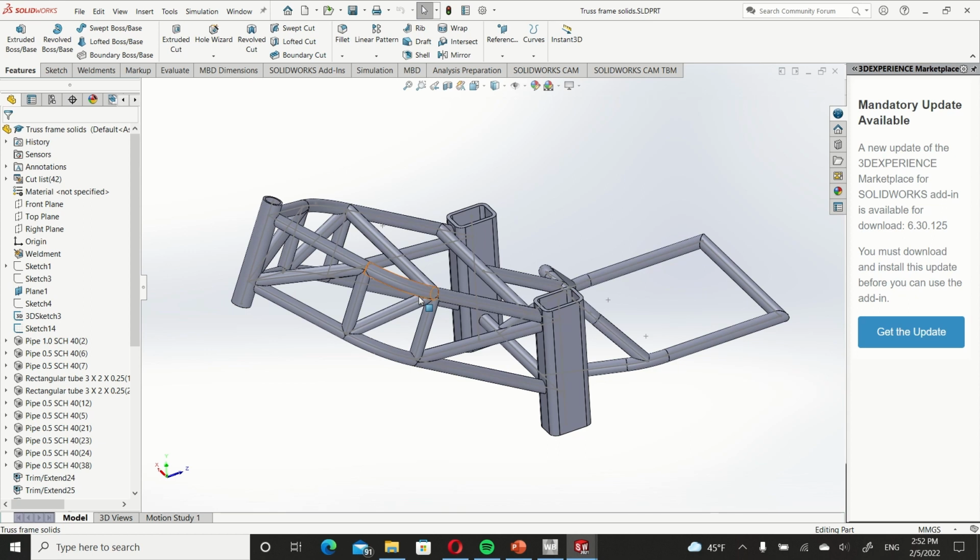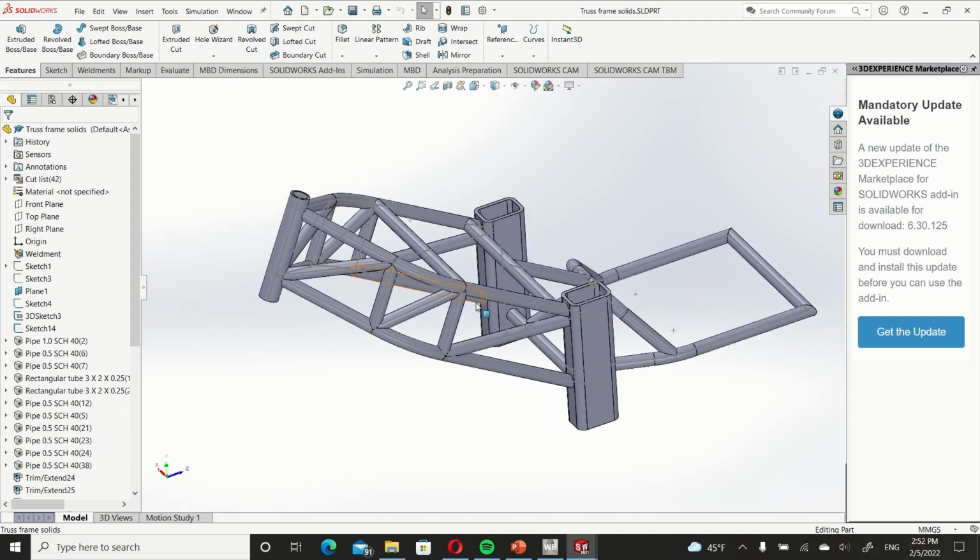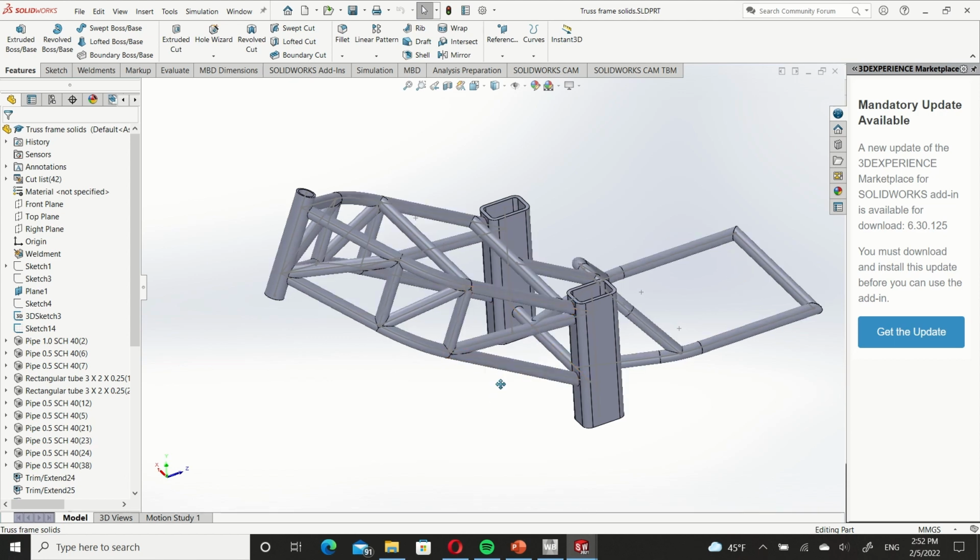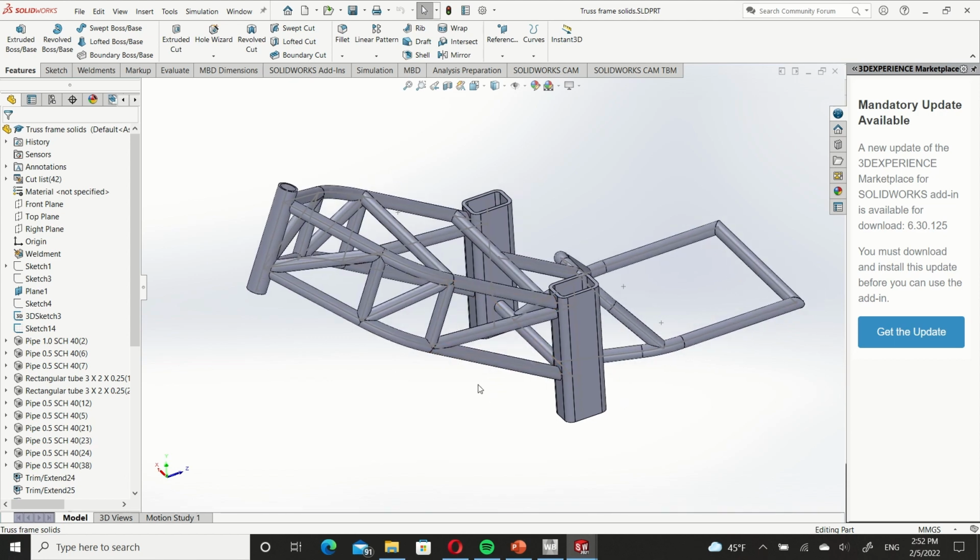So today we're going to be doing beam analysis on a motorcycle chassis. And this is a way within ANSYS to do analysis in a much simpler and, I guess, accurate way. Essentially, instead of meshing all of these solid bodies in ANSYS, you're going to tell it that each of these solid bodies is a beam, basically something of consistent profile. And ANSYS will be able to take this knowledge and simplify the meshing process by a ton and run an analysis that is a lot faster and presumably a lot more accurate to run because the entire meshing process is just insanely simple.